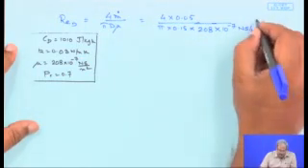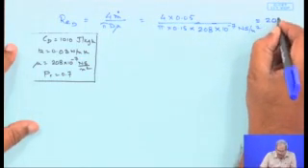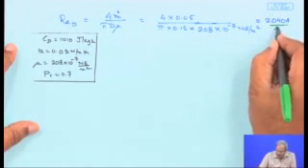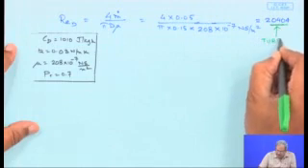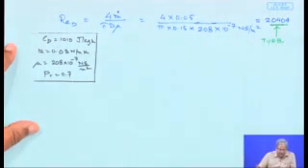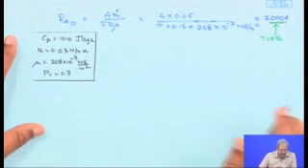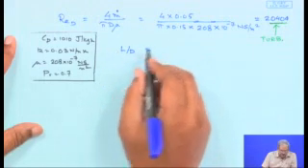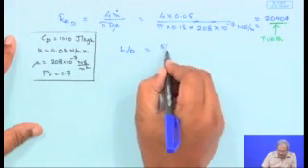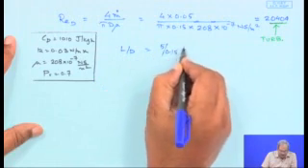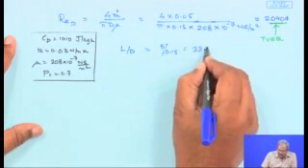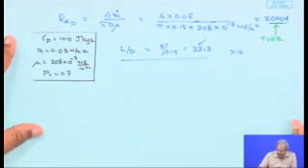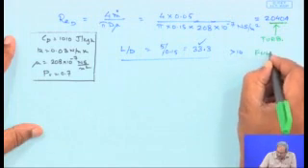So this Reynolds number, when you evaluate, is going to be 20,404. With this high value of Reynolds number, this is definitely going to be a turbulent flow taking place inside the tube. And when you calculate this L by D, the length by diameter, you would see that for a 5 meter length of a diameter 0.15, this turns out to be 33.3, and since it's greater than 10, definitely this is going to be a fully developed flow.